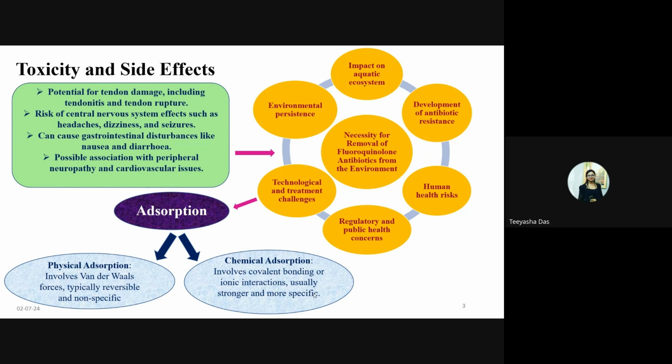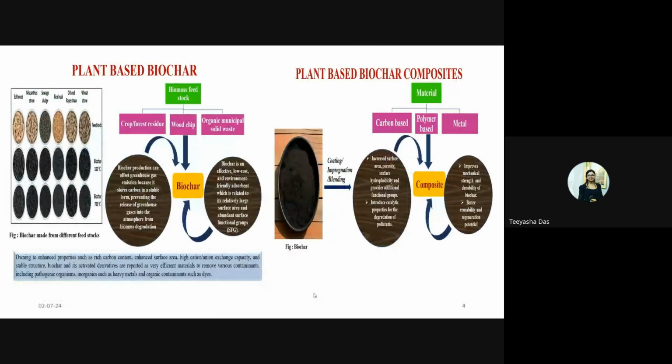Now, coming to the treatment challenges, the most widely used treatment, which has gained a lot of attention nowadays, is adsorption. Now, adsorption is of two types. First one is physical adsorption, which involves van der Waals forces, typically reversible and non-specific, and this mainly occurs at low temperature. Now, coming to chemical adsorption, it involves covalent bonding or ionic interactions, usually stronger and more specific, and it occurs at higher temperatures.